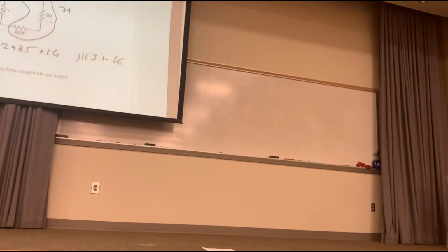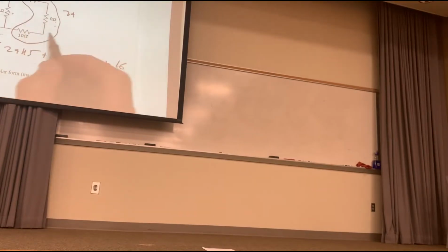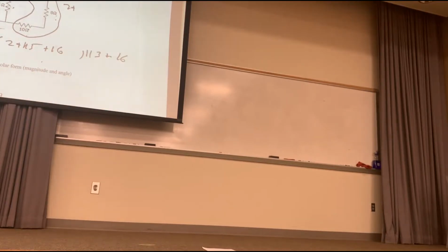Now, I'm going to go through the first part on the other test and come back to this one. This was a little harder problem. It's more involved. Same principle. Here, they're all in series. That's 24 ohms. I've got 6 and 8 and 10. It's 24. It is in parallel with 5. You all see that, everyone? That means I take 5 times 24 over 5 plus 24, get a single resistance that replaces that stuff.